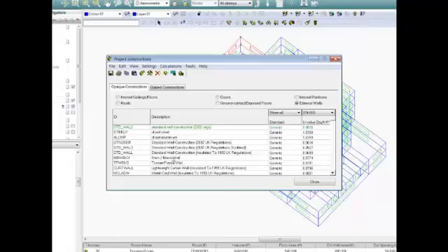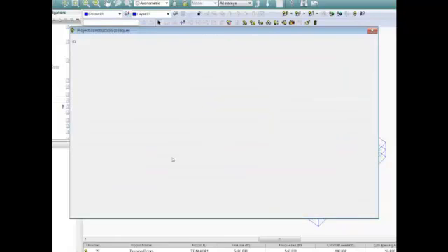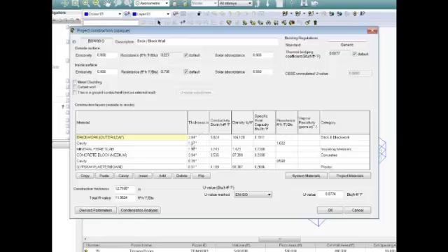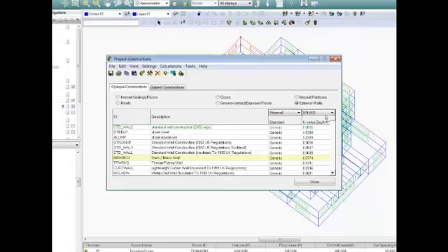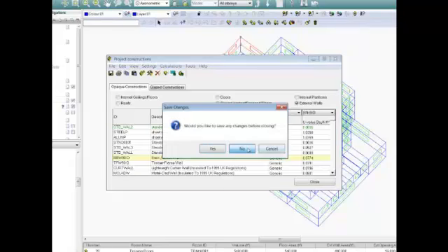I can also edit, if I want to take it further, my wall construction. So I may want to test what happens if I have, for example, my insulation. What if I take that from 2 inches to 3 inches? Because many times you'll find that insulating the building more is more effective at reducing the energy consumption than adding a large PV array. So it's really about comparing all of these technologies and even just making the building more insulated and seeing what are the best ways to improve your building design.